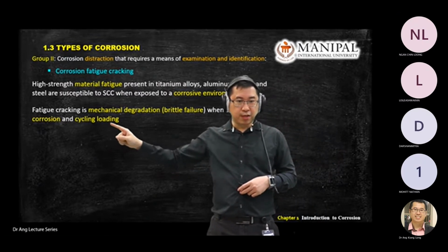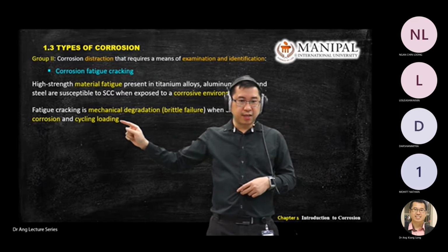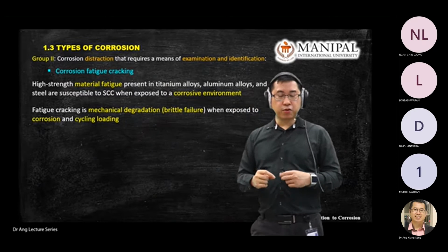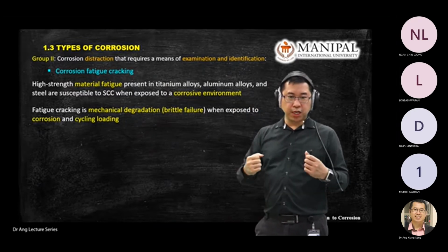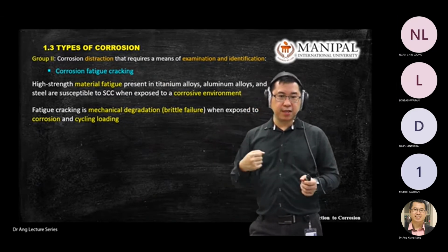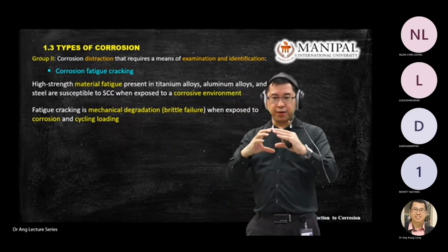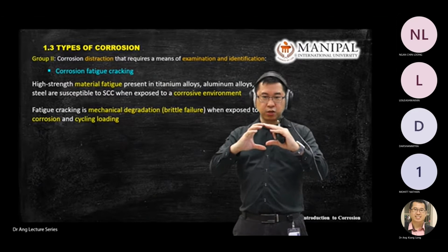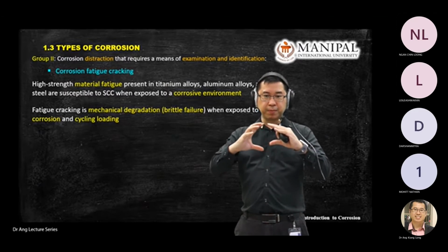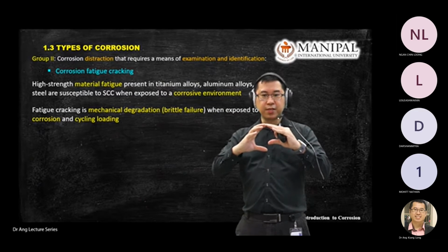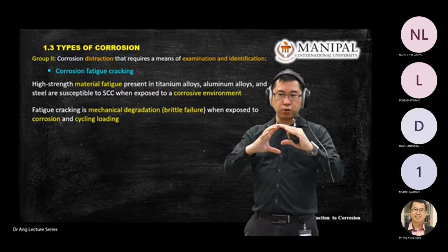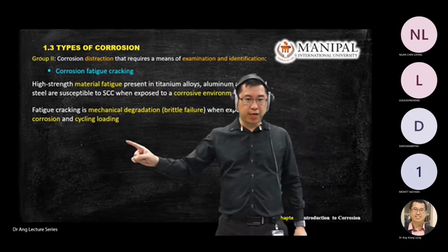Or you can say there's cyclic loading, right? So fatigue is linked with repeating loading. You repeat to load, to pull, release, pull, release, or you press, release, press, release. Or you have a pressurized vessel. When you deliver water or a solution, when you pressurize, you know that the pipe will expand because of high pressure. Then when the delivery is done, you close the valve, the pipe will relax. So if this cycle continues, you open the valve, close the valve, open the valve, close the valve, you will experience cyclic loading.